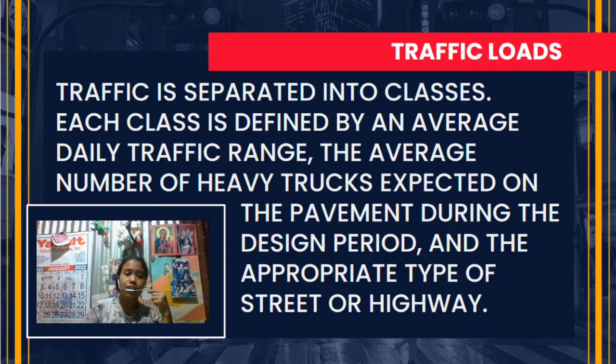Class 6 is very heavy. Unlimited autos. 7 million to 15 million trucks are expected during design period. Urban interstate highways, some industrial roads, airports over 60,000 pounds maximum gross weight. So that's all on pavement design factors about traffic loads.